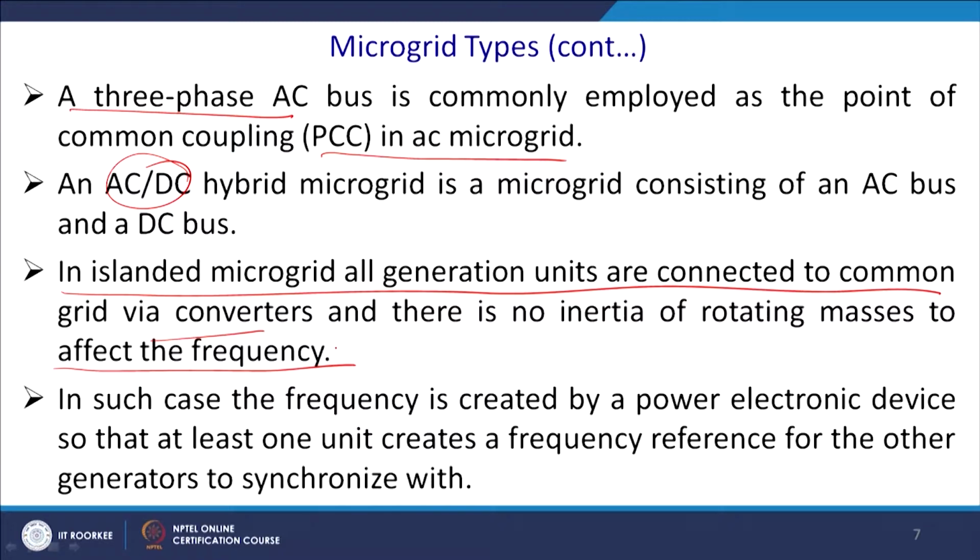Since you do not have any rotating entity and you have only the switching devices, the inertia of the system is much less than with your conventional synchronous generator. So, inertia will come down. For this reason it requires very fast action of the controller. The controller has to act quite fast compared to your SCADA and conventional grid.